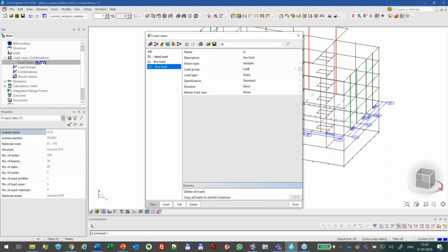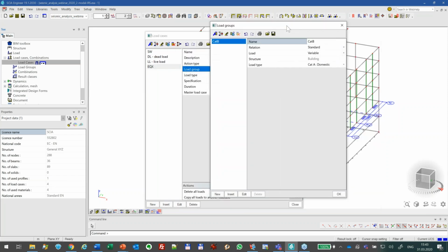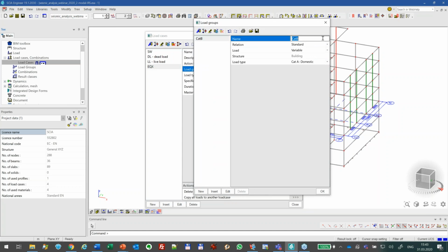First of all, well, obviously, creation of a load case. So let's call that earthquake X. That's going to be this. I need to create a separate load group. So this is a variable load case, obviously, variable action. But here, as I said, new group for earthquake action. The type of load here is different. I'm going to select seismic here. It's a particular variation of the accidental loads, actually, and this one we want to have in this setting. And I'm going to select here together, which allows me typically to create afterwards the seismic combinations with combining the earthquake action in X and Y direction.